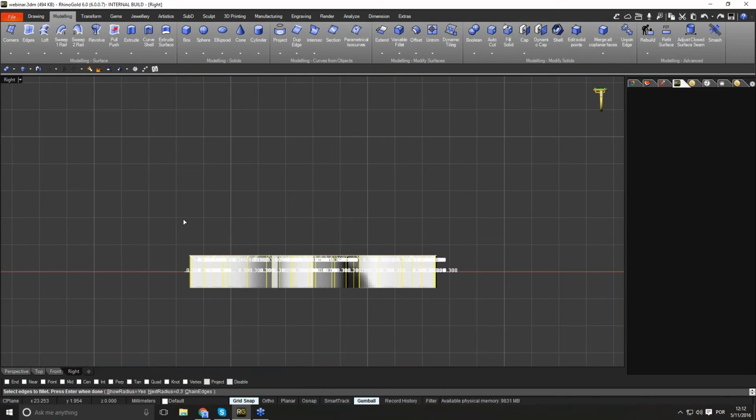And in this case, let me just repeat to adjust the fillet angle. I will type first the fillet angle, maybe 0.15, enter, and I will select my edges, enter, and now I will apply the fillet to the selected edges. So at this point it's calculating the fillet to all the edges.